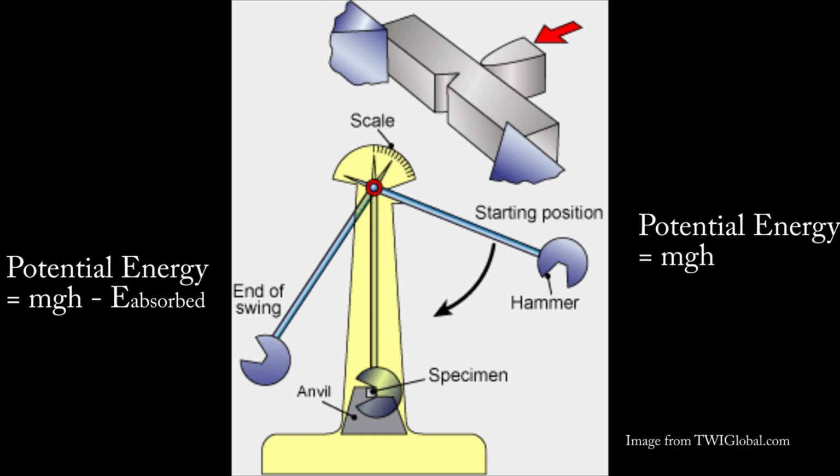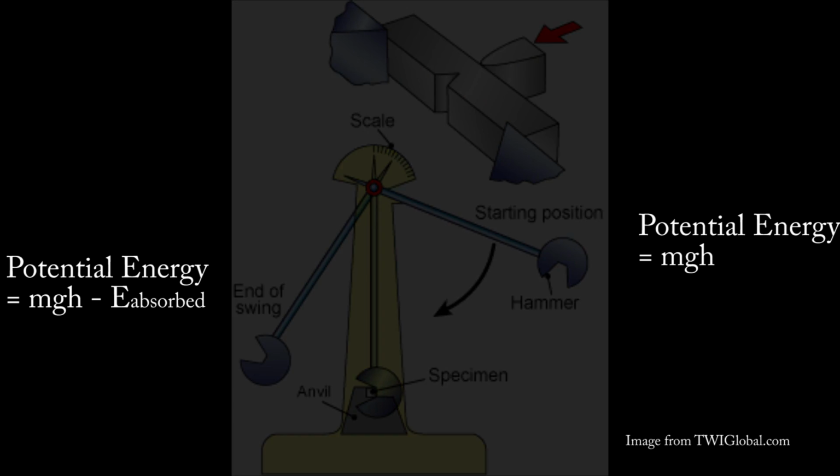So a lot of times we're concerned with not just how strong a material is, how much weight it can hold, but how does it respond to impacts, how does it respond to cracks and things like that. And the Charpy energy value gives you an idea. You can't actually design with it like you can a strength value, or there's a different type of toughness called fracture toughness. Those two you can design around, but the Charpy energy value really allows you to quickly compare different materials or different treatments.